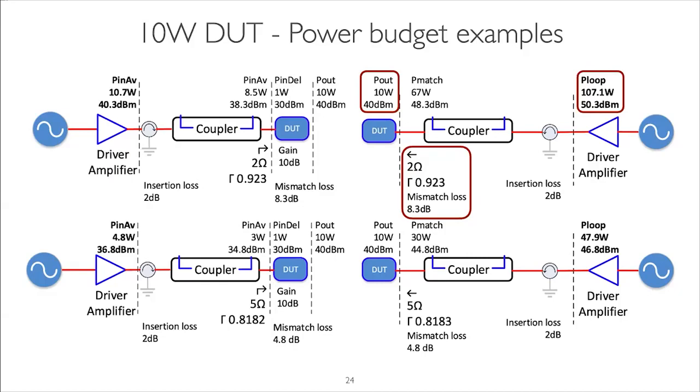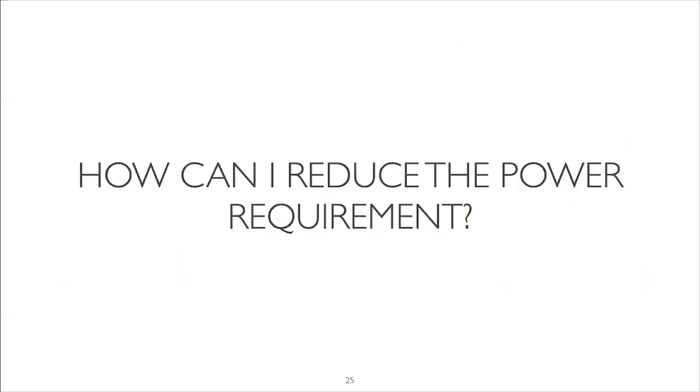But again, if you go into higher frequency, you look at 5G applications and millimeter wave, you're going to have a tough time finding an amplifier that has more than 10, 20 dB that's affordable. Okay, so this is something that people always take for granted. They think that the active will just take care of itself, but there's a lot that goes into finding the right windows of operation, both on the input and on the output for these kinds of applications.